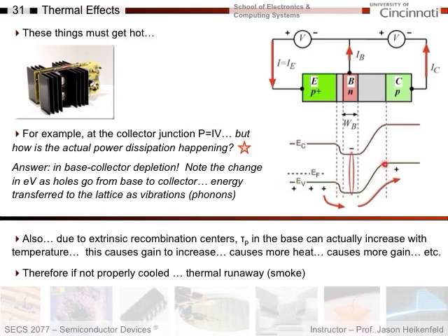band diagram. I have holes, I kick them over here, they move through and out the collector, but look what's happening here. Remember, for holes, they float up, right? So their highest energy is when they're further away. Like an electron, high energy is up here, a hole with high energy is up here. So as they get closer to the bands, they're giving up energy. Look what happens here with this hole.